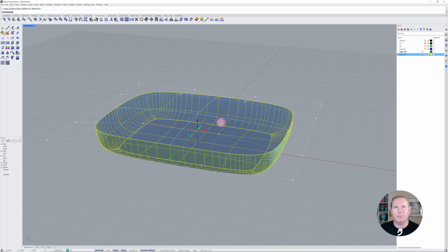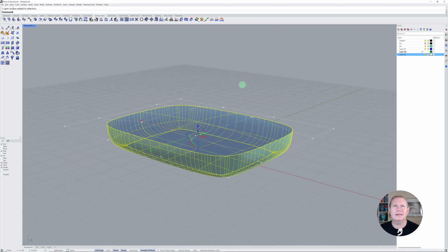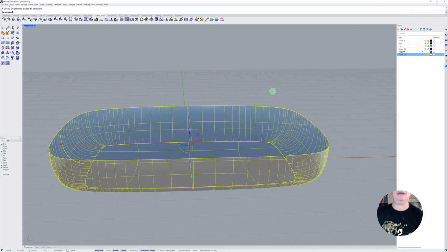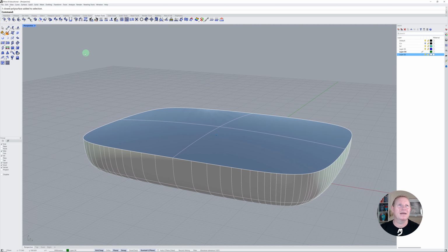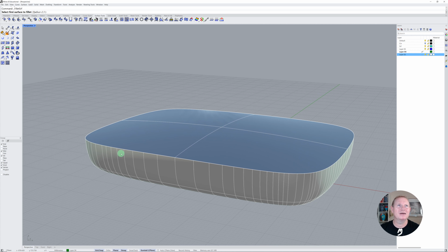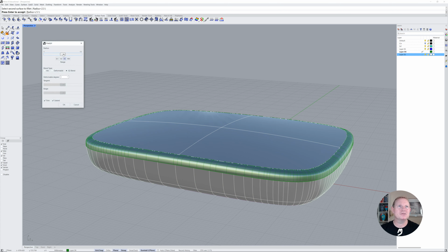Let's just select the top, and then let's try joining that now. And we can see that now, because we had a good top surface topology, that the whole lot has joined in one go. And we could do something like we could fillet this surface and then select the second surface and choose a radius, and we could do a G2 blend.